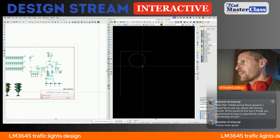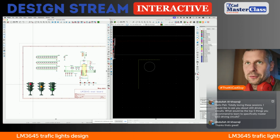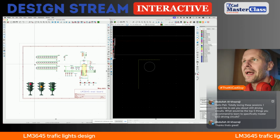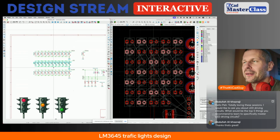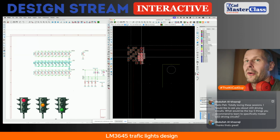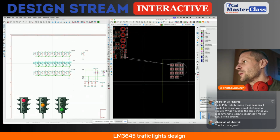So I will start with a simple circle put in the User.Drawings layer, and then, as on a common traffic light device, the semaphore, we have the red LEDs on the top. So now I am selecting all red LEDs in the schematic, and KiCad automatically selects all those components here. So we have 11 LEDs to be placed here.